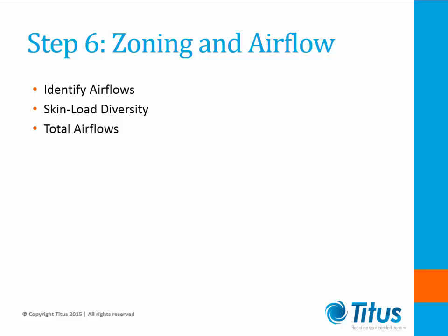As the sun progresses throughout the day, the airflow required by the perimeter zone will change and the supply air totals in the building will move around to follow the sun. If you are utilizing duct runouts for your primary air system, those duct runouts will need to be designed for the sum of the peaks of that runout. If you're using a main duct loop instead for the primary air, you'll need to include the diversity in those calculations.